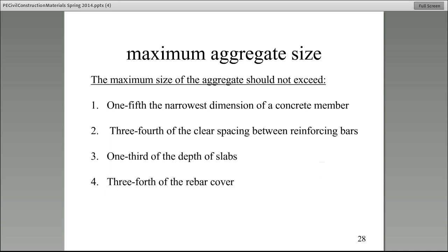All right? Now, step number 2, and guys, this is very, very important. Step number 2 on page 23 refers to the size of aggregate. In this particular problem, they say 1.5 inch. What if they don't give it to you? Many questions have been on the test asking this. All right?